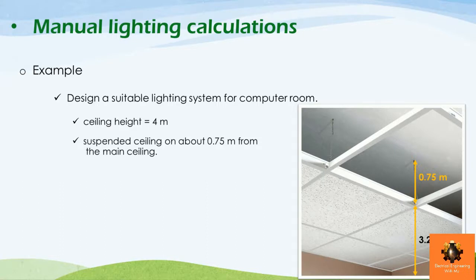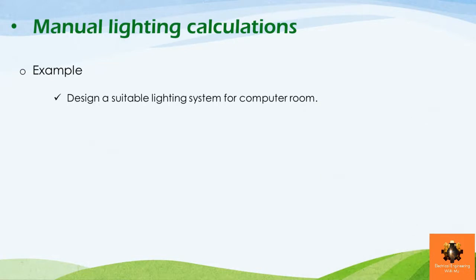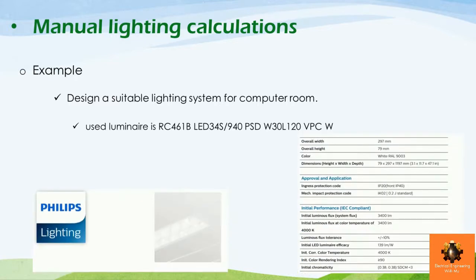Very good. After that, for the luminaire which we will use, if we search for that code, we will find its datasheet and see that this is an LED luminaire, and this is a piece of the datasheet of this luminaire. Here its manufacturing company is Philips. But the important piece of information for us now is the lumens out of this luminaire, as it's 3400 lumens. Here we can detect it easily from the datasheet.